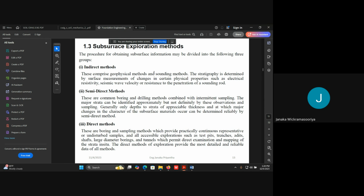So indirect methods, what we do is we measure some other parameter, and we interpret the data to get the soil parameters. These comprise geophysical methods and sounding methods. The stratigraphy is determined by surface measurements of changes in physical properties such as electrical resistivity, seismic wave velocity, and resistance to the penetration of a sounding rod. So we measure the other parameters and come to a conclusion about the soil parameters by interpretation.